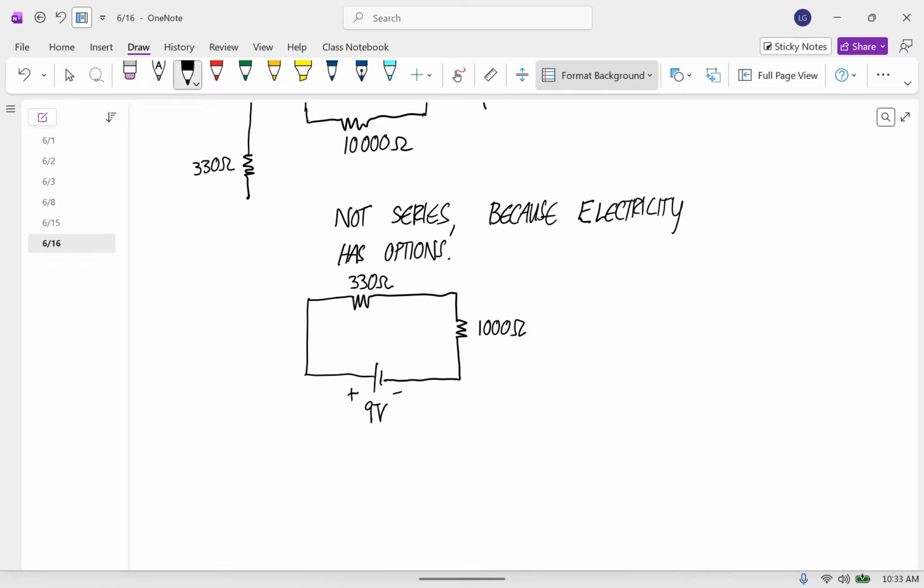So now the path of the electric current is locked in, and so the currents through everything have to be the same. Electricity can't go into a corner and hide. All it can do is just keep moving around that path. If you only give it one path, the current's the same all the way along it. So this is resistors in series.